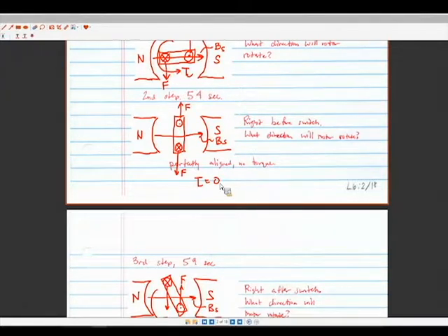So what does this all mean? This one's easy. This is basically how DC brushed motors work. This is the main functioning behind the internal guts of a DC brushed motor. In terms of what this means to you as an engineer, DC brushed motors are for the most part the least expensive of motors. They're everywhere, especially in servo-controlled systems. We'll talk about servo-controlled systems in this class quite a bit, which is how we do a lot of positioning tasks or velocity control tasks.